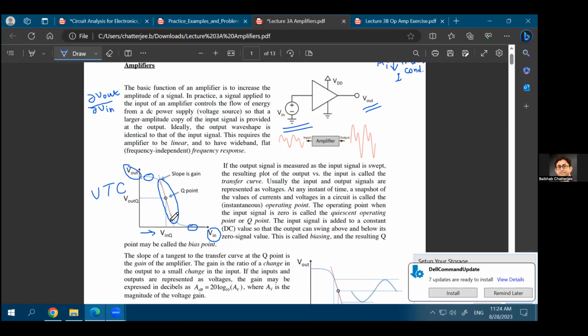So we talked about two very important things here, even if we didn't realize it. First, the amplifier amplifies only AC inputs. It does not amplify DC inputs. But the DC voltage has to be near the middle of its voltage transfer characteristic so that you can expect gain out of it. Let's assume the y-axis as well as the x-axis are divided between 0 to 100. If your voltage swing is between, let's say, 3 and 5, you do not see any change in the output. When your input swing is between 97 and 99, again, you do not see any change in the output. But if your input swing is between 49 and 51, you see a huge change in the output.